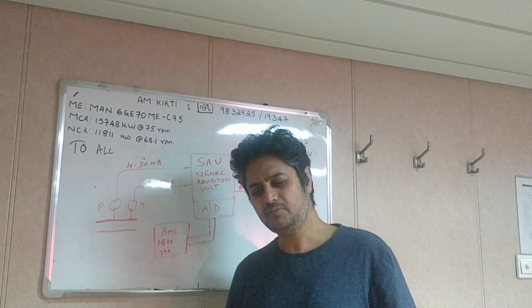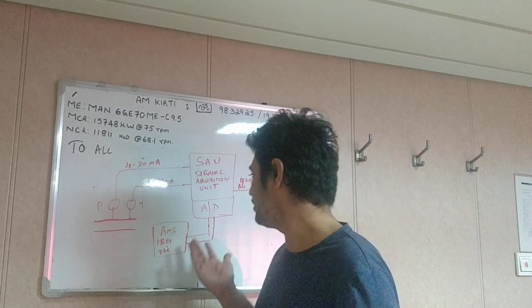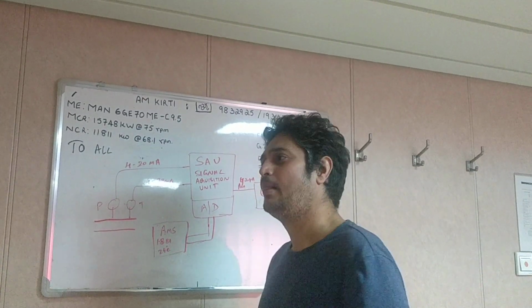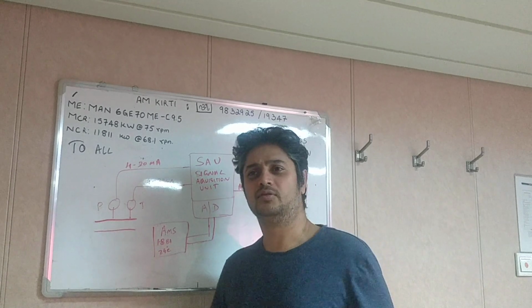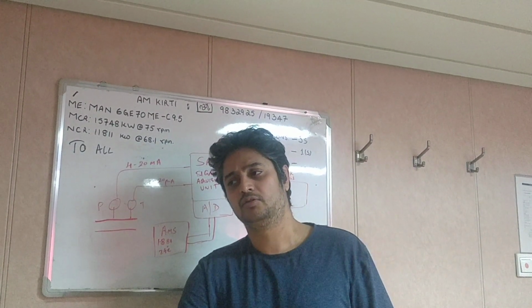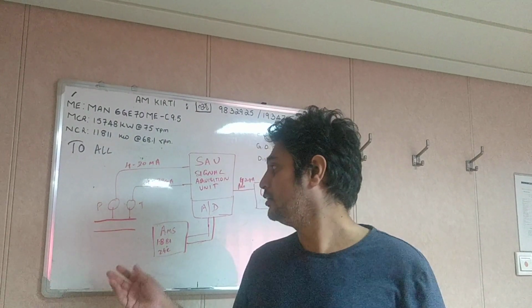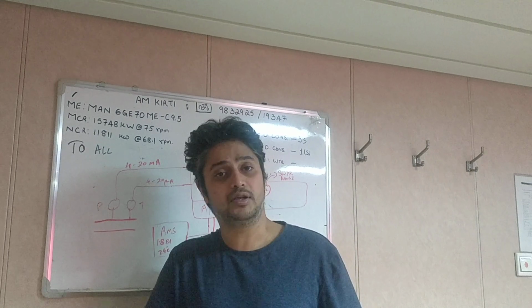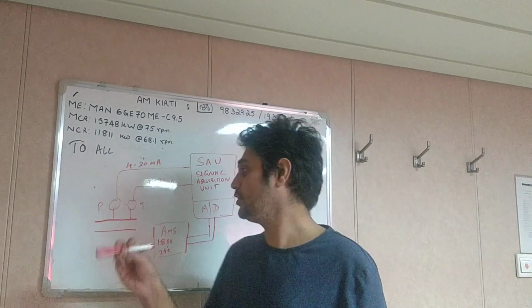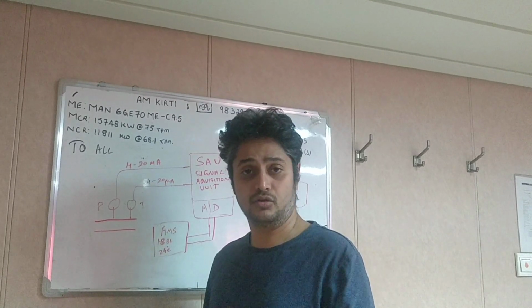So where can things go wrong, what faults may happen in this system? You would have noticed the electrician saying the sensor is faulty. How does he tell that? He will check the continuity of the sensor, and in case of a pressure sensor, by checking the continuity, it should show some value.